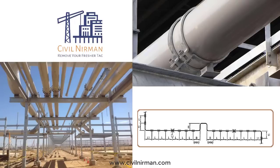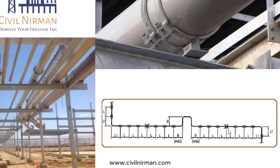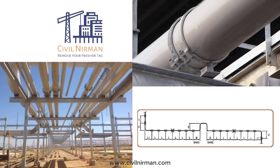Right now you won't be able to understand, but just let me explain that this particular diagram shows an anchor support. So in one particular line, two anchor supports are provided, while the rest of the supports are guides. That way we can understand what load will be coming and the location where we have to apply the load, which can be explained in a detailed isometric that will be provided by the piping discipline to the civil and structural discipline.